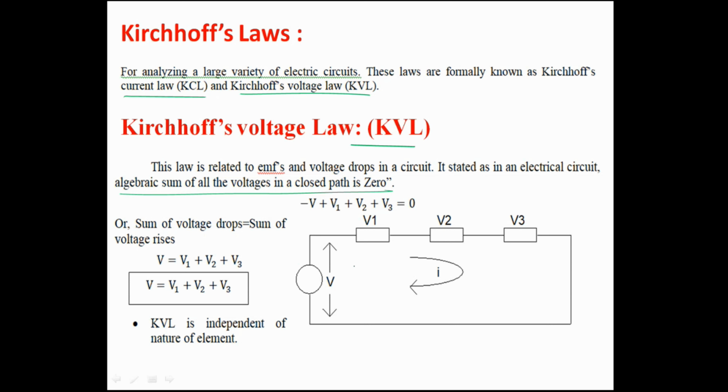So in this example, if you take this circuit where you have a source with plus and minus, and these are some passive elements, maybe resistor, inductor, capacitor, which we have discussed earlier, right? Whenever current flows in a circuit through passive elements, we all know that the voltage will drop. When will the voltage drop? The voltage will drop when the potential is dropping, that means when the current is flowing in this direction through this element, maybe a resistor or inductor or capacitor, whatever it is. So the entering terminal becomes positive and the leaving terminal becomes negative.